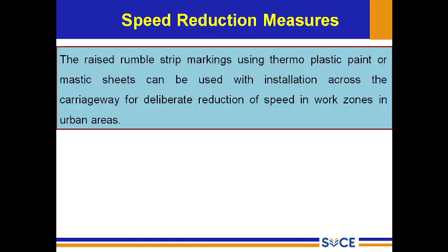Especially in India, circular humps are widely used. The profile of a circular hump is based on the shape of a circular arc with a radius varying from 11 to 113 meters. The 113 meter radius is a very smooth curve with a chord length varying from 9.3 to 9.5 meters. It achieves a desired speed of 20 km/h to 50.